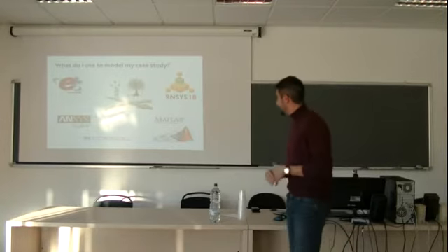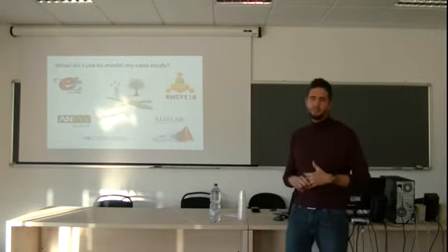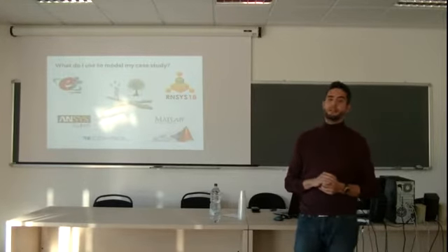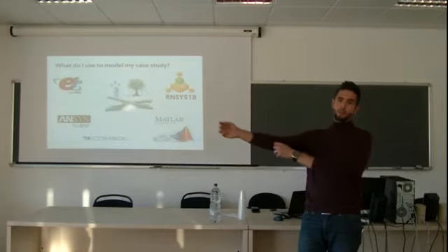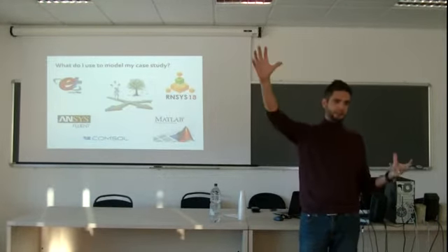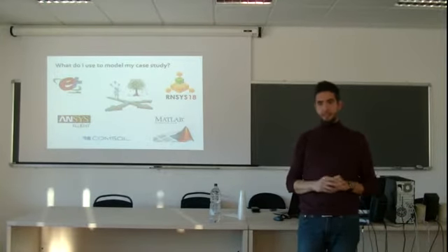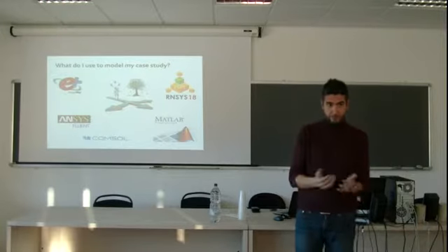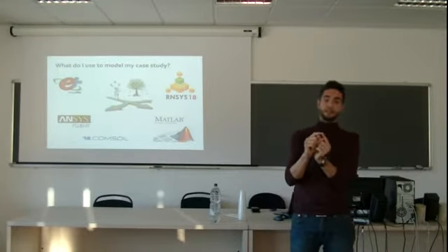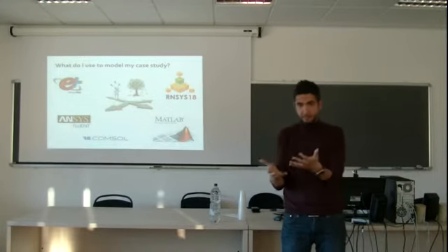Finally, we have TRNSYS. Also, you have to pay for that. This is in case you want to simulate a system. Imagine you are simulating a solar field with a seasonal storage tank coupled to a district heating network. The good thing about TRNSYS is that the models are already there. You have a black box model of a solar field. You can control temperatures and so on, but the model is already developed.